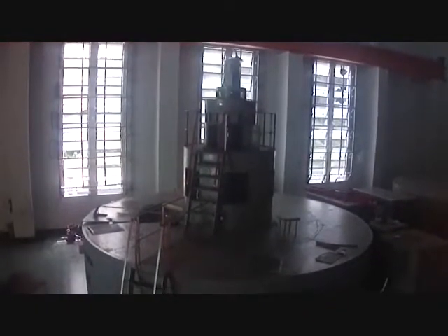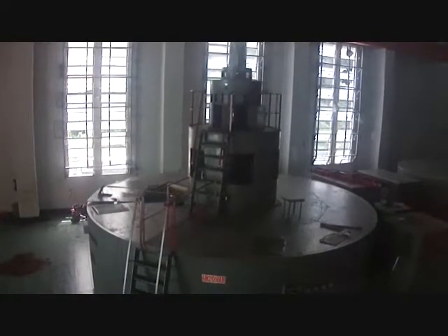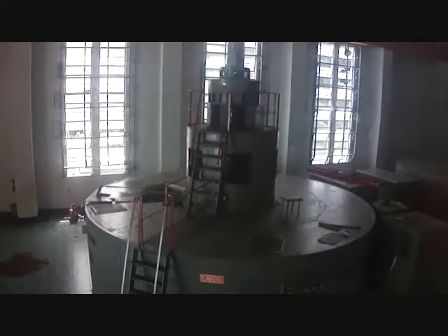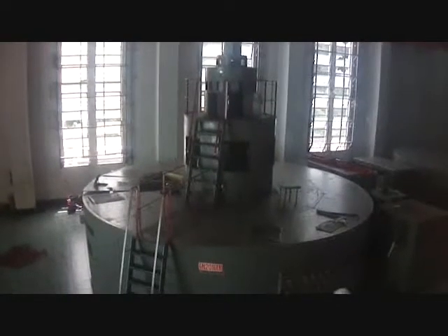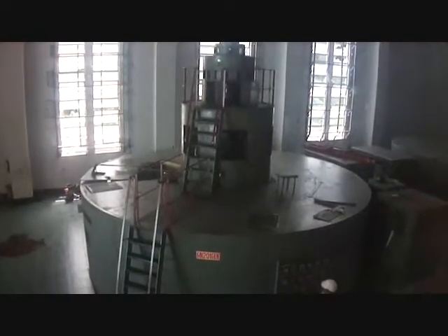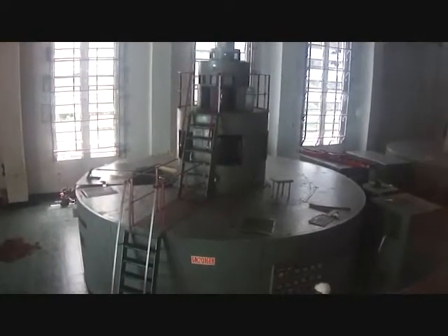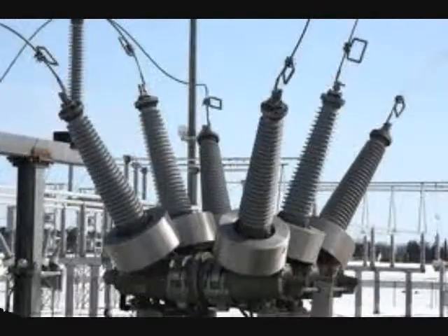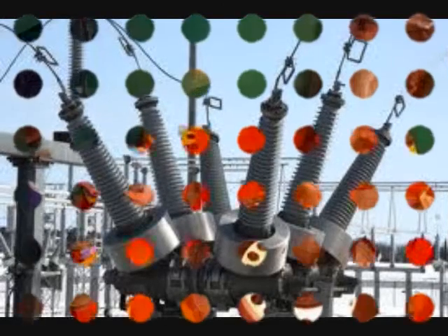The DC current for the rotor windings is provided by excitation systems. In the older units, the exciters are DC generators mounted on the same shaft, providing excitation through slip rings. Today's systems use AC generators with rotating rectifiers, known as brushless excitation systems. The generator excitation system maintains generator voltage and controls the reactive power flow.